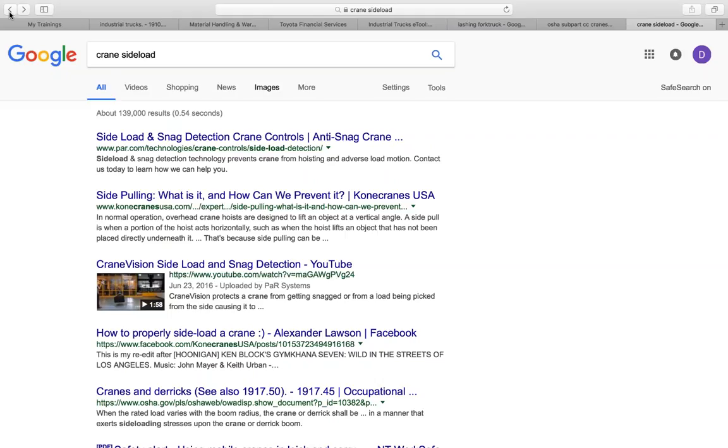But at the same time, let's say we only use slings that are 15,000 pounds apiece and we have 4 slings. We're going to calculate it on the weight of 3 slings, because we count 1, 2, 3, and the fourth also counts as 3. I think we talked about that about 4 weeks ago. When we count slings in a bridle, let's say we have 15,000 pounds, we multiply by 3, whether it's a 3 or 4 leg sling bridle.